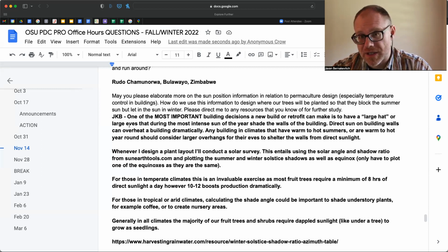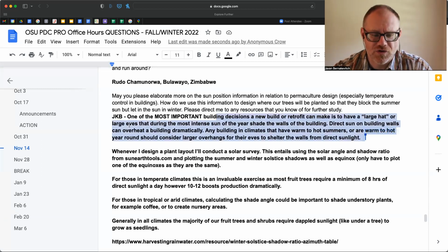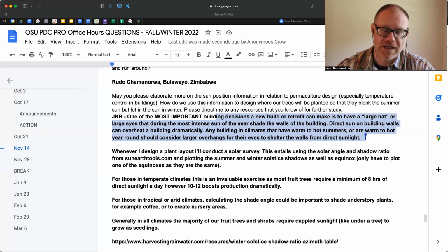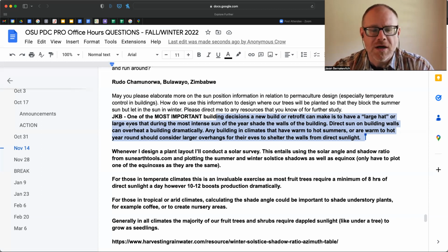The other thing you can do then is you can start to work with different types of trees in terms of their foliage and making sure that that foliage works with your climate and your climate change and the ecological change that happens with it. So within Canada, in a couple of our designs, we would have deciduous trees that would leaf out and were as tall as needed to be to shade different areas of a house or houses that didn't have good eaves. So that way the sun couldn't come onto the sides of the buildings.